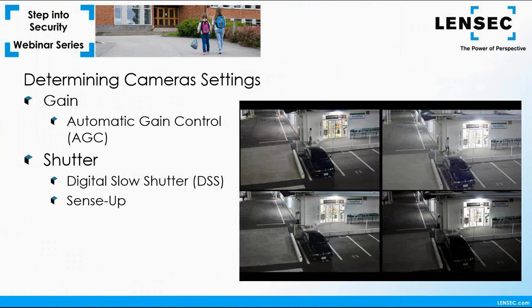Gain control is a critical factor in low light surveillance video. It's generally only noticeable when the negative side effects of gain levels are seen, namely noise or snow on the screen. Noise is displayed as graininess in a low light image. Ideally, you should attempt to achieve the lowest gain for a light image that you can achieve without noise in the picture. Your gain is measured in dB.